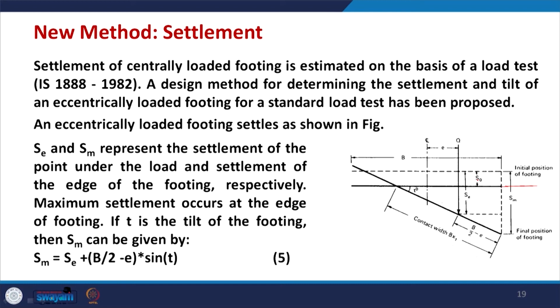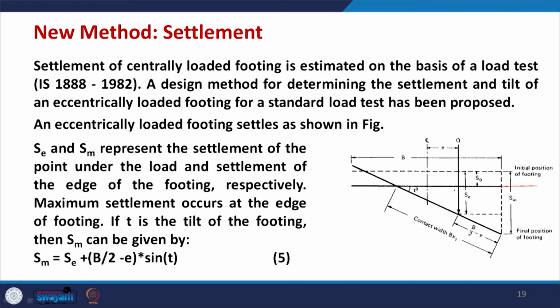However, if your load is acting more on one side, then one part of the footing will settle more, another will settle less, rather it will be tilted, which could be seen here. It is expected that towards the load side there is more settlement, and the maximum settlement is at the edge.